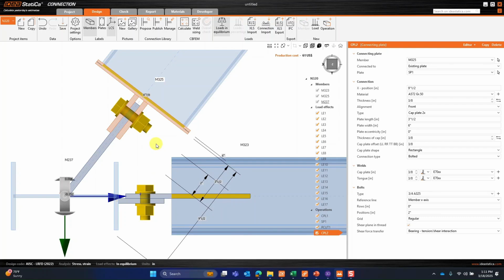And to find out the overlap length for these two plates, we can always open up the measuring tool. From here, I'll go ahead and select two edges or corners, and from there, I'm given the overlap, which is 3 inches. And as you can see here, the initial position now is at 2 inches. So we'll go ahead and adjust this to 1.5 inches.